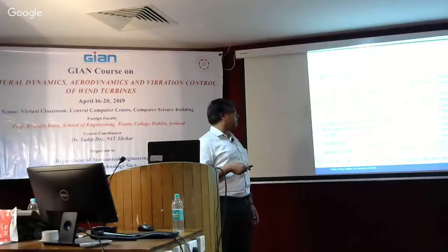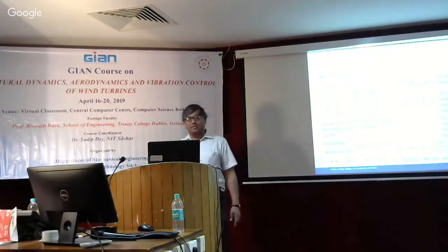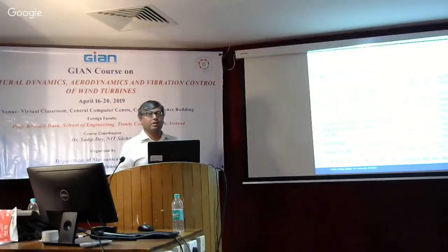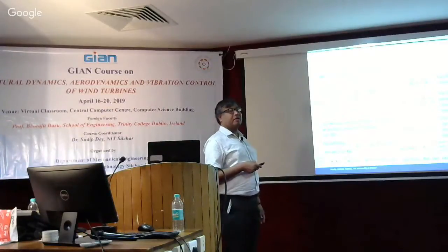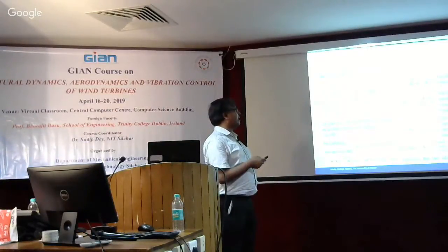Minimize the objective function, then we can solve it by solving an algebraic equation called the Riccati equation. And if we use that, then obviously we can find out the gain matrix from there, provided the state matrix A and the control influence matrix B is known to us. So this is our A matrix. You can see with A and C in it.